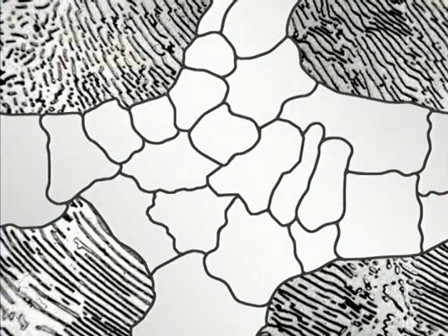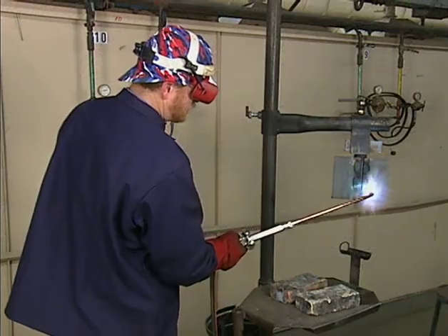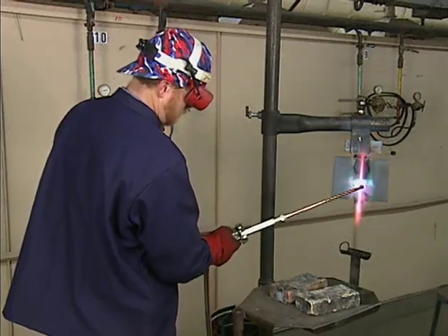How steel transforms from austenite, which exists at elevated temperatures, into ferrite and pearlite when enough cooling time is available for carbon to diffuse. How a brittle structure called martensite forms when you let medium and high carbon steel cool too quickly, and how you can use heat to control cooling and return ductility to embrittled steel.